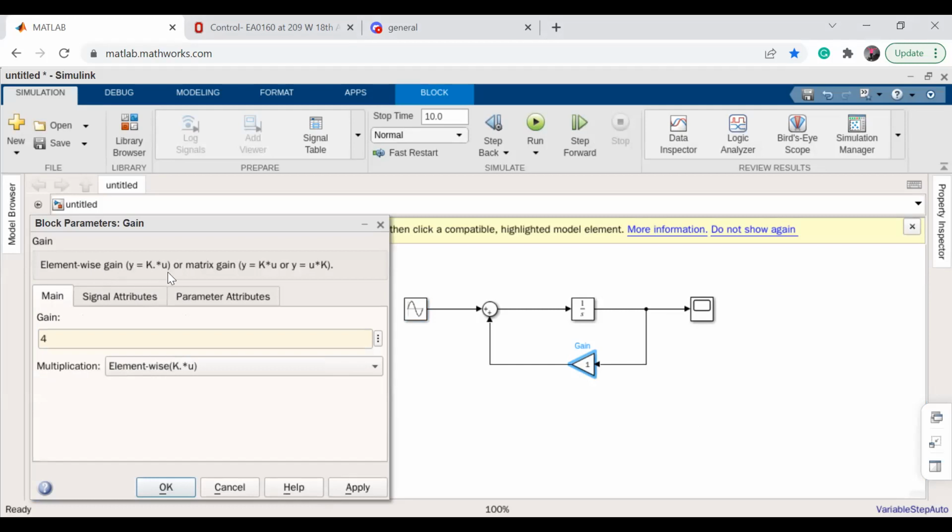We can connect our Simulink model to our MATLAB code. If you run code in MATLAB and introduce a value m equal to something, and put m here and connect that m to the workspace in MATLAB, it will copy it here. A lot of the time we build a general model and then we change our numbers in our code. All right, so this is how you connect the attributes.